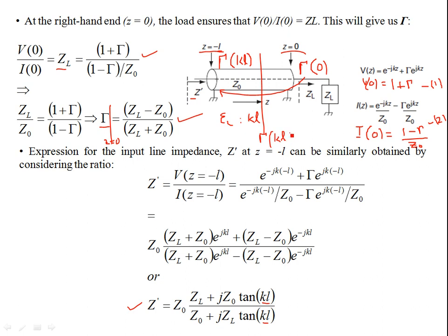And well, it's not very hard to come up with a general formulation of gamma, just like the transformed impedance. This is the transformed impedance. So what about the transformed gamma? Okay, transformed gamma, you see, if you recall the basic definition, that is the reflected part divided by the incident part. So I'm going to make this a function of Z first of all, because gamma, the reflection coefficient, is going to change down the line wherever you are in terms of space coordinate Z. So this is given by the reflected wave, which is, let's call this gamma.